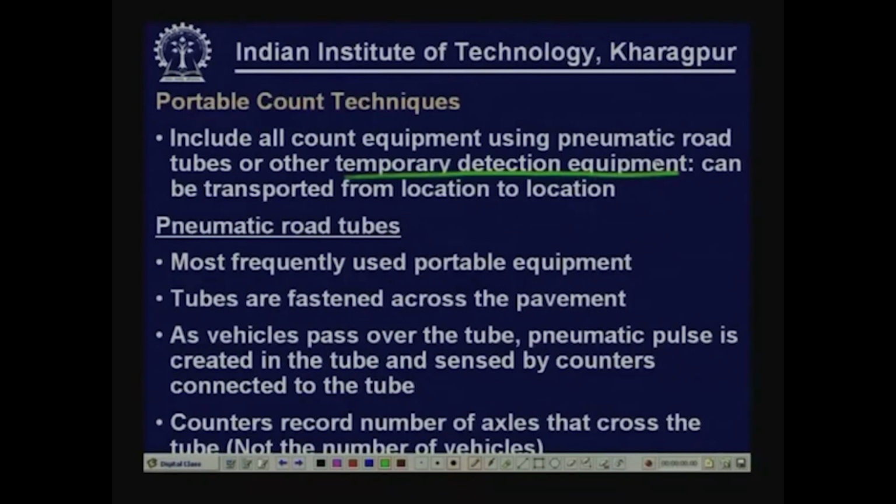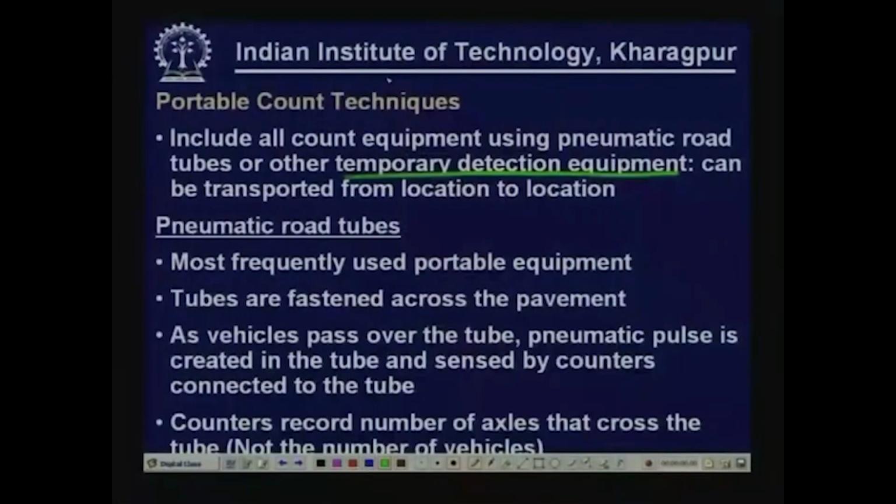We are calling it portable count technique because the pneumatic road tubes or temporary detection equipment can be transported from one location to another. You have carried out traffic volume studies at location A, you can take the whole setup and go to location B. So, we are calling them portable count techniques, that is why the term portable is coming.